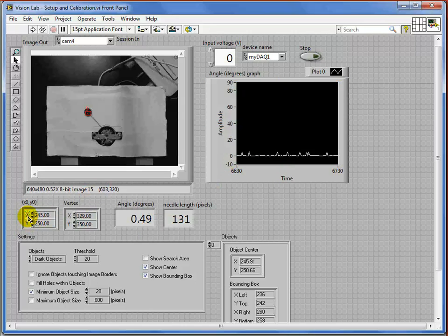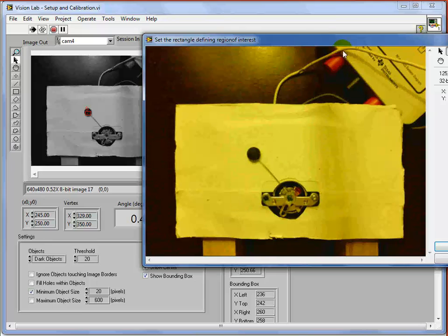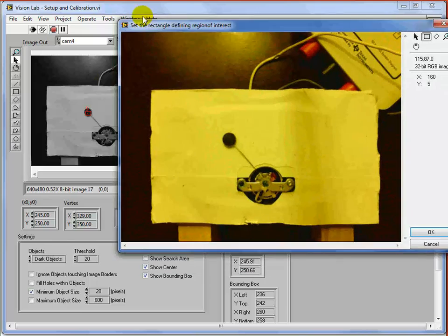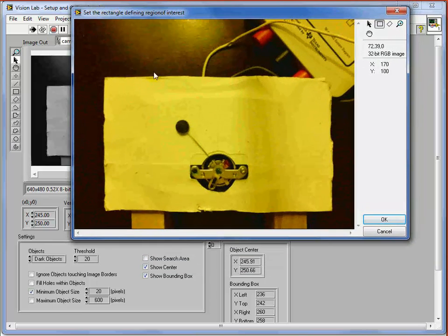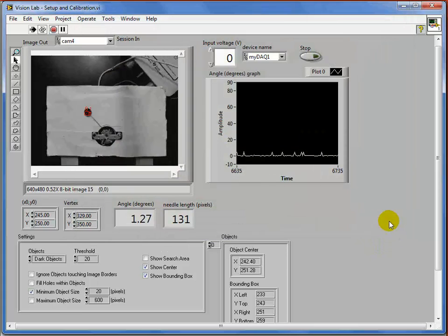As I said, you can adjust these after we get going, and I'll show you how this operates. Keep this brief. So again, you run this, it starts with the camera, acquires an image, and right away says, hey, find an object center. So now we want to find that 0 point. You can do this by just selecting a region of interest here. Say OK. So now it's going to find that point 0 there, right?